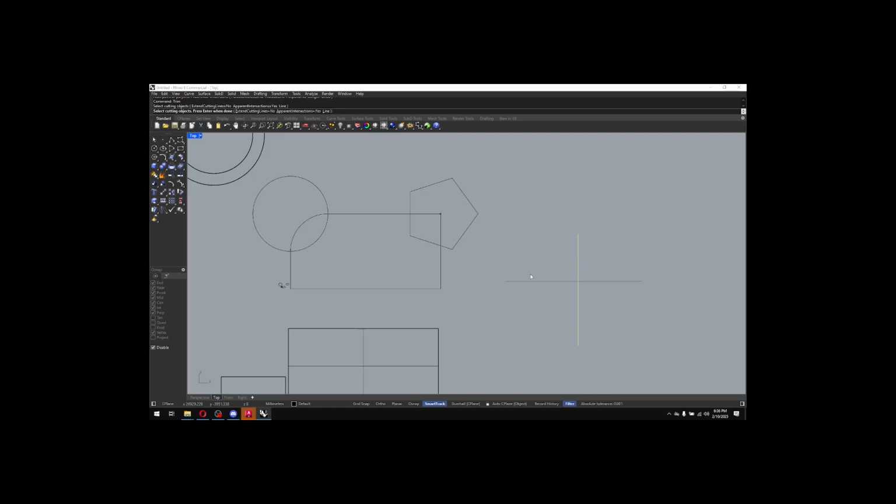This is my scissors I'm going to use to cut through. Select object to trim. So now I'm selecting the piece of paper that I'm cutting off. So if I want to cut this piece off of paper, that's what I'm selecting on. So again, I'm clicking right back into the same command. Select my scissors, enter, select my piece of paper I'm cutting off, and you just click it and then enter and you're done. Just like how it works in AutoCAD.